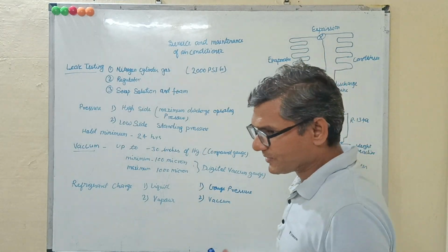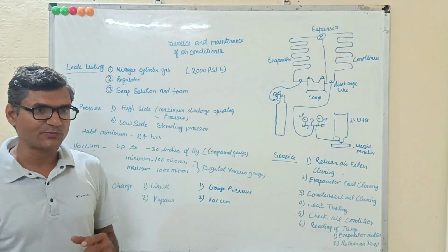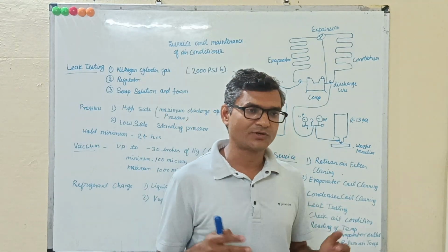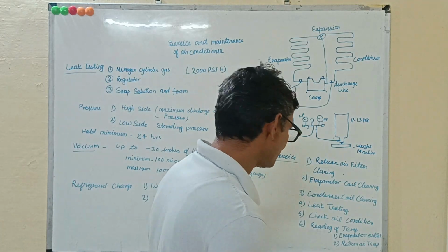If the compressor has a side glass, then we can see the oil condition. If it is yellow, it needs to be changed. If it is totally white or transparent, then this is a very good condition of the oil.